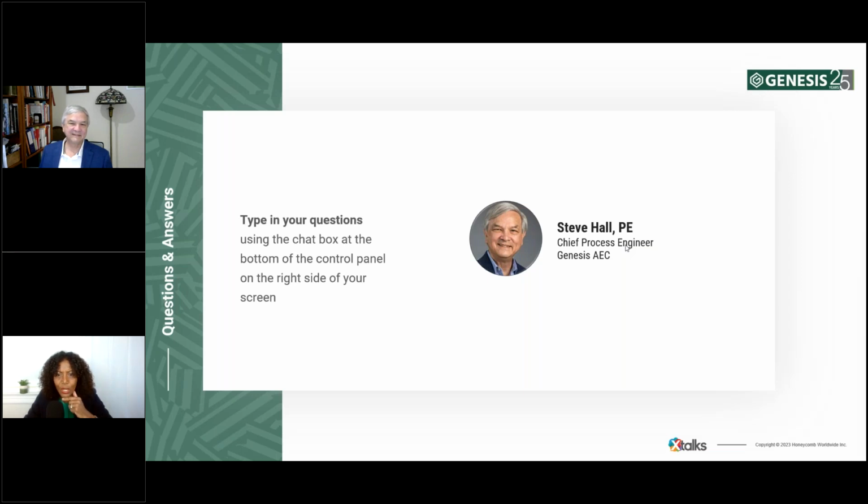So this audience member here asked, when is it appropriate to run a deterministic model versus a stochastic model? That's a good question. I really did emphasize the importance or interest in running stochastic models. But before you just start running it stochastically, it really helps to do it deterministically without changing the inputs to help debug the model. So a lot of times we'll run it with a fixed set of inputs to debug it, and then follow that with starting to vary different elements. And also, kind of like a design of experiments, you can vary different inputs individually to see how that affects it. It's a way to find what your design space is and which of the inputs have the most effect on those outputs.